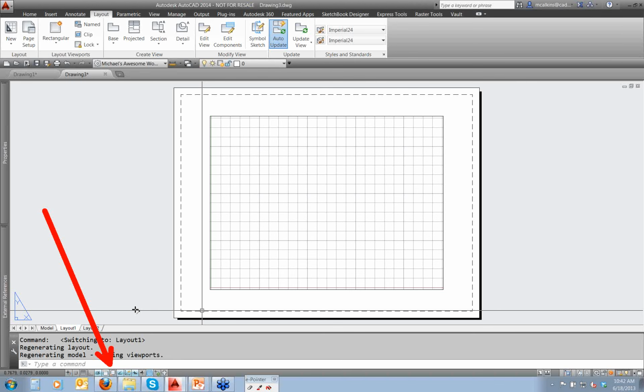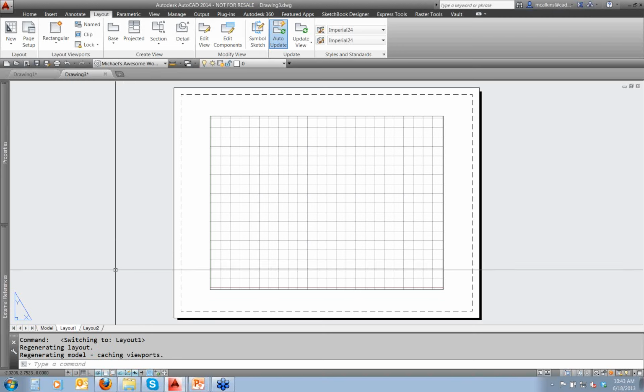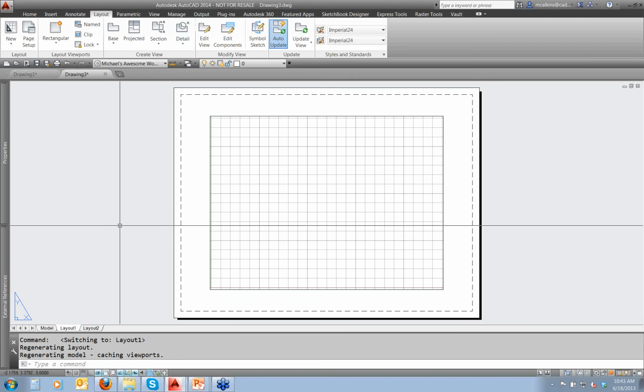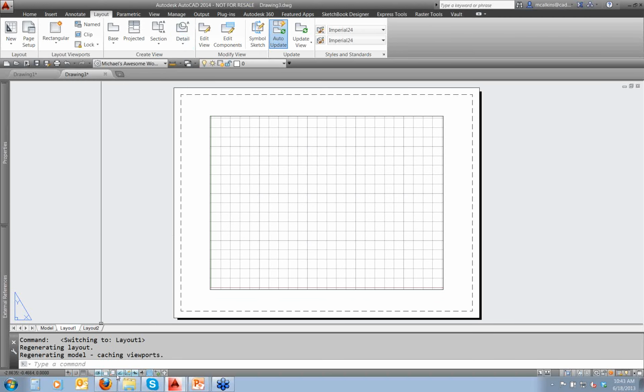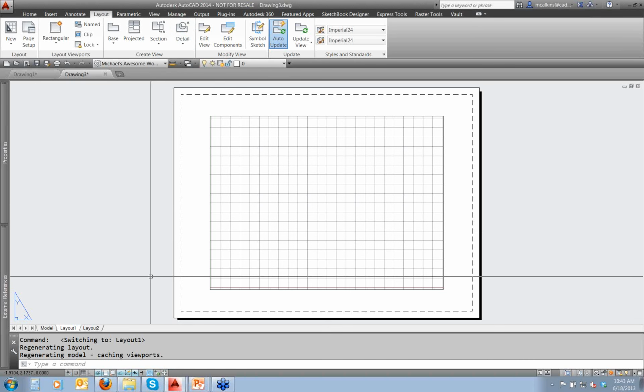I can toggle on and off my ortho and the grid and various tools, O-snaps. And we've done that before using F keys. That was pretty straightforward in the early days that we used our F keys. Later on then what they gave us was a little list of text down here. For some reason in 2009, I guess they just went to a more graphically oriented workspace, they switched to all these icons down here. I know what they all do just by looking at them now. We're all familiar with buttons. However, you might not like those.